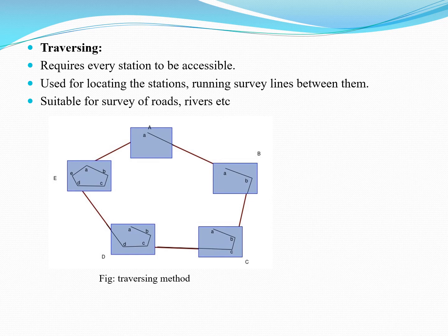All the arrangements are done as per the setting of the table. The setting of the table means centering and leveling. So after that, the table is oriented towards point A by any one method of orientation to make the connections with the next stations. So whenever you shift the position of the plane table, you have to do the orientation by using any one method.